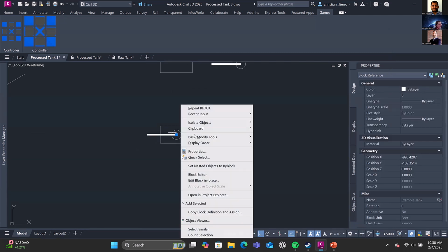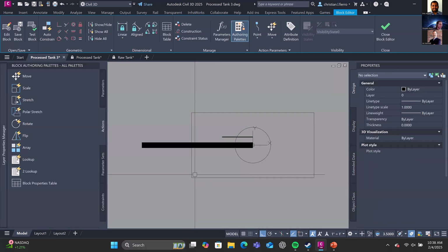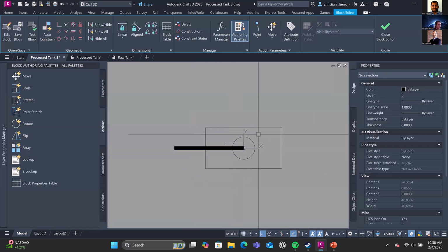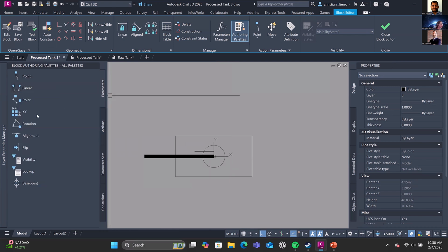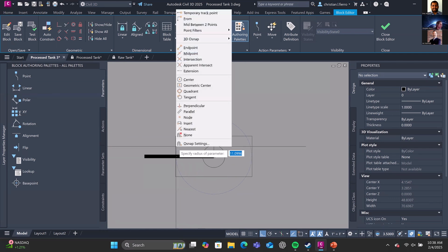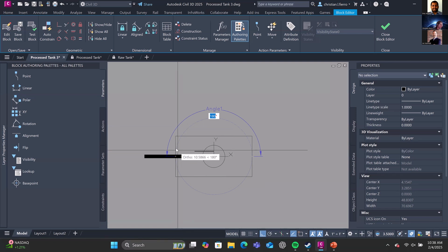Now we go inside of here and we know that we want to create some part of independent control. But again, we're still conceptualizing this. We're still working through this. So we don't want to tie ourselves into a position to where we're having to redo our work. So what we want to do is create a rotation parameter. Let's say I'll use my starting point, my 0, 0, 0 origin point, and I'll select, let's say, my mid of my base here.